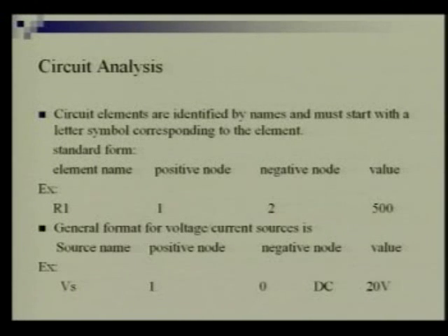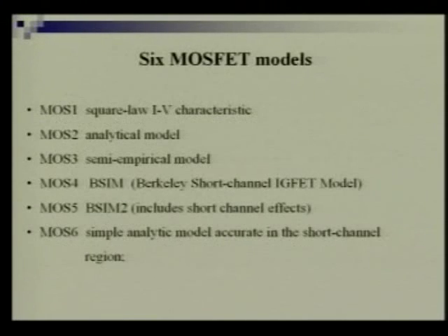So this is the way we just give. Suppose we are giving the previous this, what is the element name, what is the positive node, what is the negative node, what is the value. That's the way you are to describe to the SPICE.